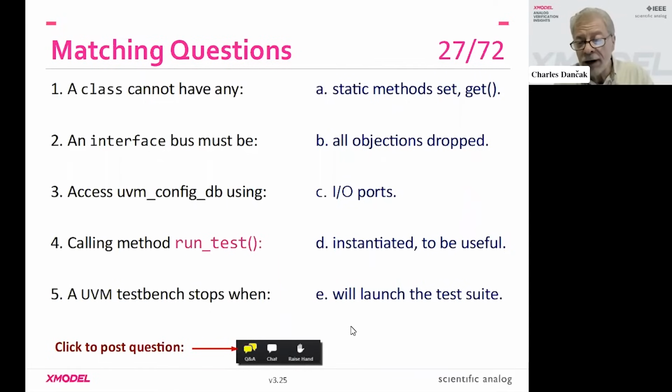You've got it collected in this nice, handy, named bundle that you can instantiate wherever you want on the chip. So although you could do the same thing with just plain traditional Verilog signals individually, in a complicated system on chip design, it can save you a lot of low-level errors and hair pulling by having this named bundle called an interface bus.